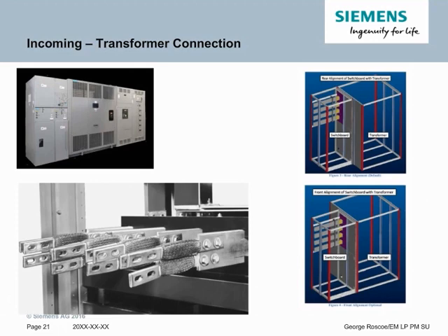The flex cables absorb vibration, therefore preventing screws from coming loose on the switchboard side. These are only typically used for transformer connections to unit substations, so these are fairly rare. Probably less than 2% of the volume is a transformer connection. But it is very critical when designing these that you specify the transformer, just like the busway, to ensure we put the connections in the correct spot.